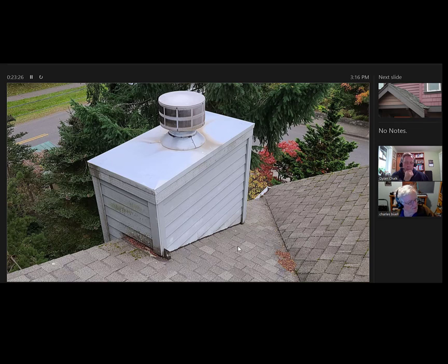That's probably one of the most difficult areas because nobody wants to put a cricket there, because then the face of the cricket shows over the edge of the roof. Yep. It doesn't take much slope though. You could install that flashing. But then you see the realistic problem here, which is all the debris ends up clogging it.